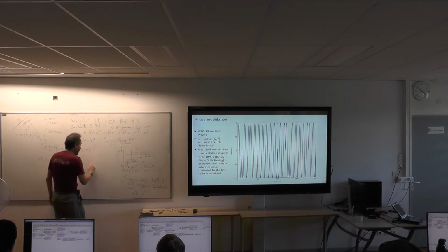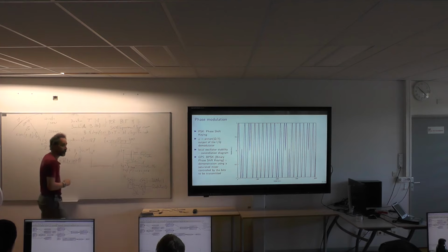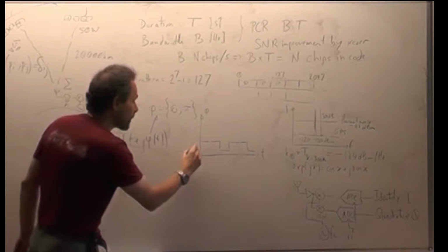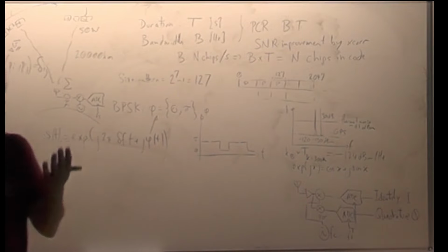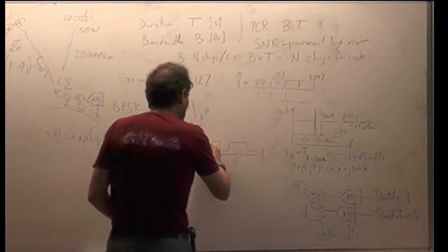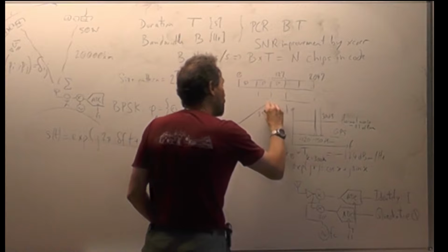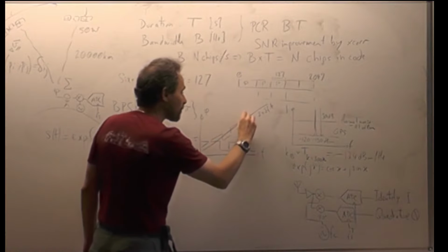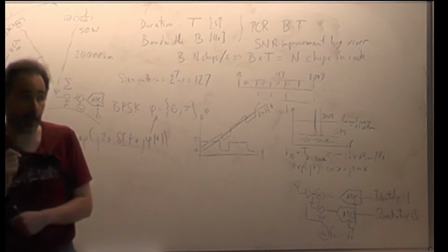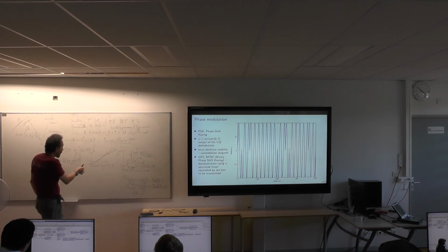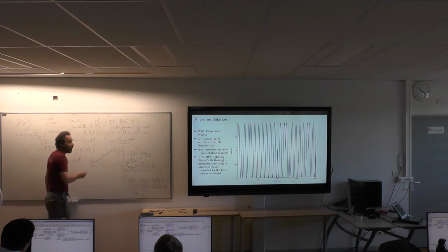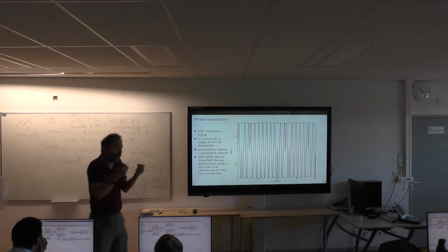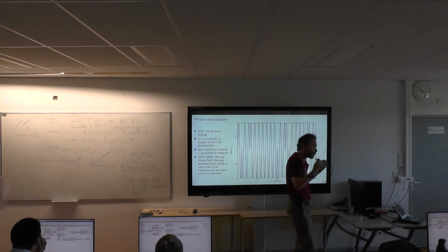So what does this mean? It means that if I plot the phase as a function of time, I would want something that looks, for example, like this. That would be my phase sequence equal to 0 or pi. But because we have a leftover frequency offset of delta F, you actually have a slope which is 2 pi delta F t, and your phase is coming on top of this slope. So this is actually the phase that you're going to detect. And you see that it's going to be very annoying, because if I have, in addition to my phase jumps, this phase rotation due to delta F, it's going to make the decoding very difficult. So you must find a way of canceling delta F, the frequency offset between the spaceborne clock and the ground clock.